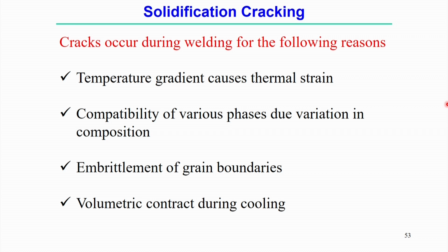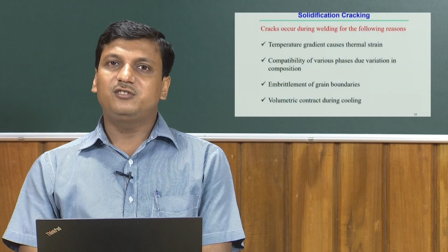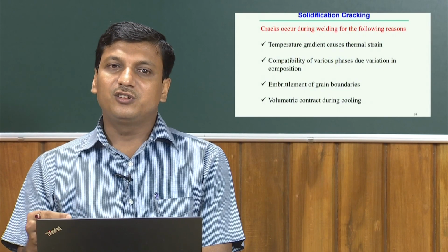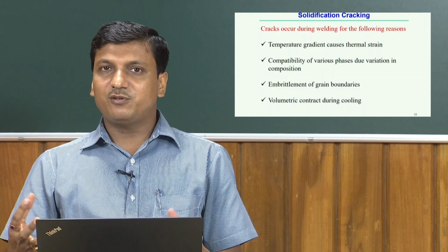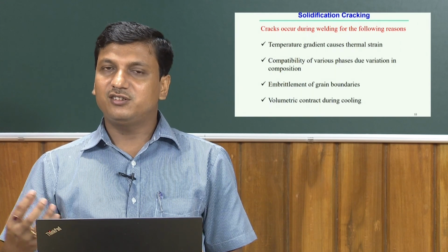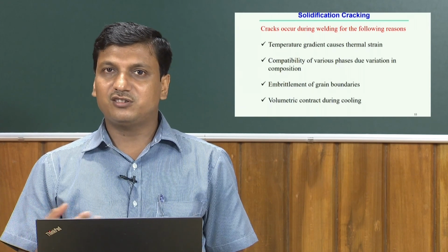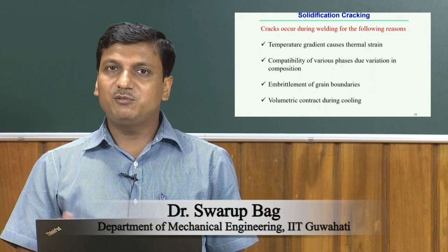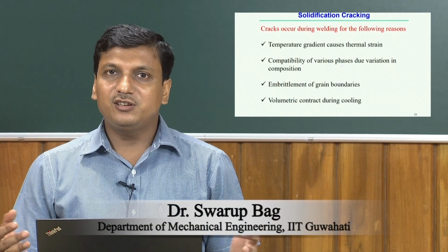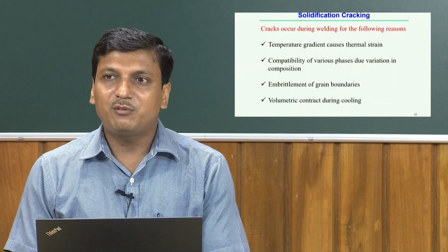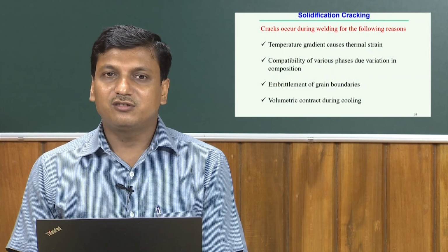Sometimes if the grain boundary becomes embrittled, that induces solidification cracking, and another reason is volumetric contraction during the cooling process. Different phases have different constitutions, so during the cooling process there is a change in microstructure, and due to the changes in the microstructure there may be a contraction in volume that may induce some amount of cracking during the solidification process.